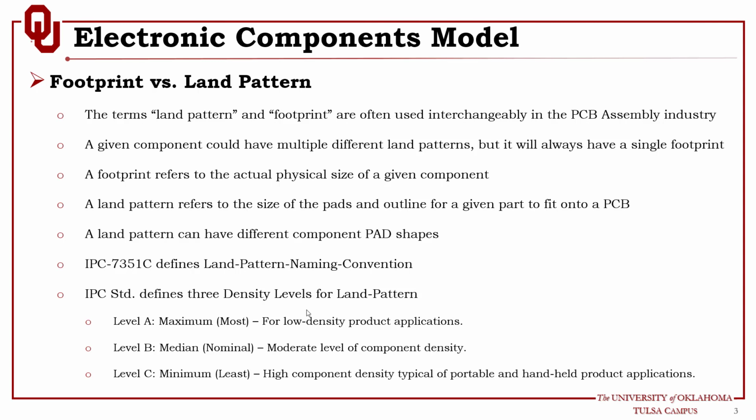Now, when it comes to the PCB assembly process or PCB soldering process, in both cases, whether manual soldering or automated soldering, they require that the pads on the printed circuit board be larger than the leads of the component.